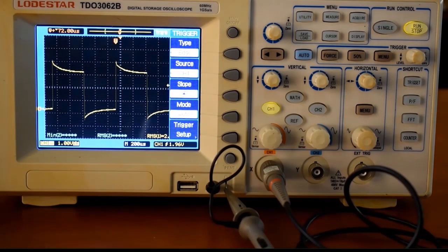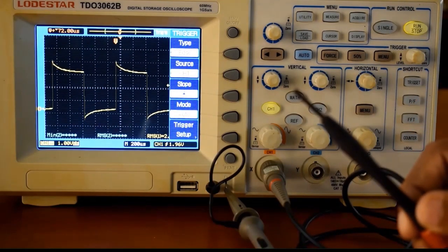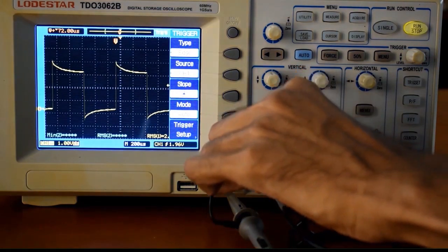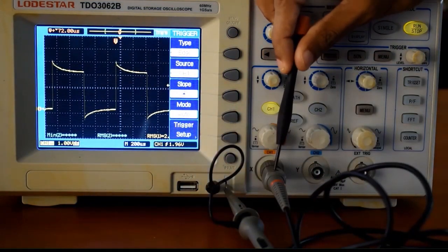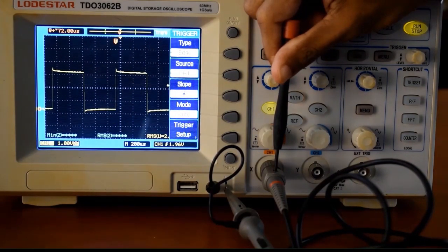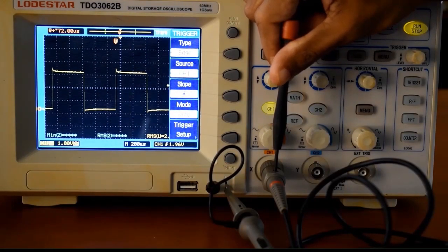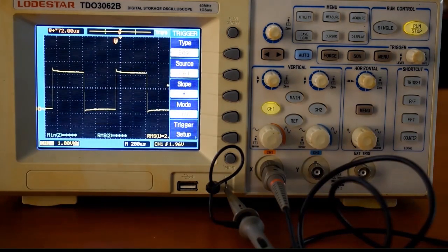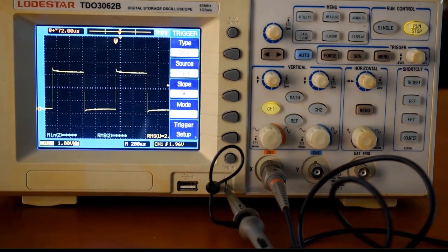Now, these highs and lows should be completely flat, as we assume the oscilloscope is outputting a near perfect square wave. If not, it is because the compensation capacitor in the probe has not been tuned, so we are actually measuring the signal incorrectly. Using a tiny flat screwdriver, adjust the screw head in the probe until the square wave has straight edges. Note that some probes have the compensation adjustment near the probe's plug instead. Now we have everything set up to take a voltage measurement. The oscilloscope is now ready to take measurements.